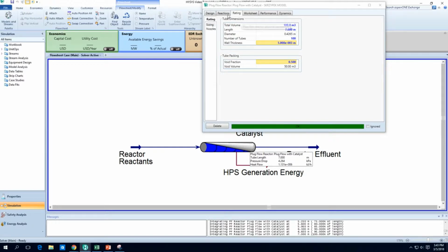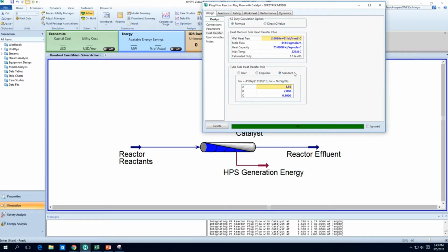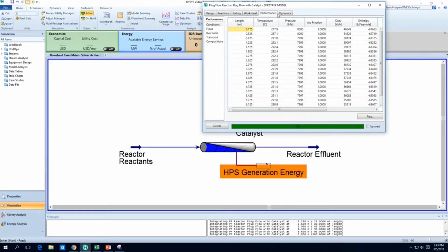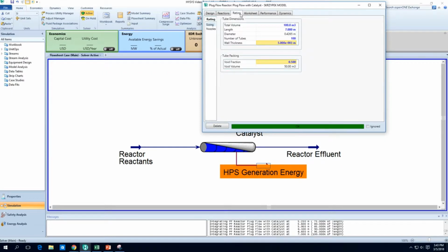but the thing is that your heat transfer is a lot better. See, it's 314, that's almost double of the last time, because you effectively increase your area quite a fair bit. So that's how you get HYSYS to automatically calculate it for you.